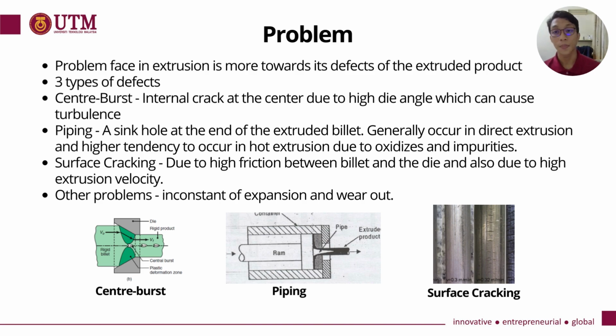Other than these defects, some problems that might occur are inconsistent expansion due to inconsistent force applied to the ram, and wear out, which is caused by the friction between the die and the billet while the extrusion process is running.